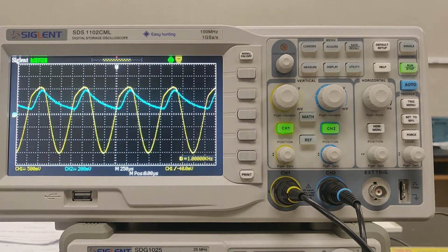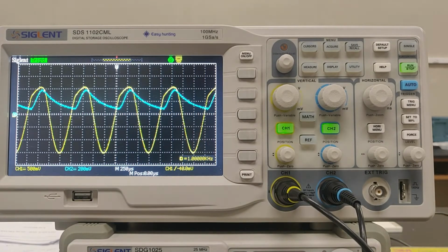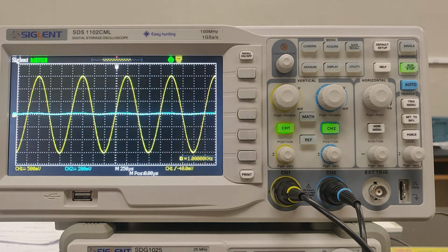So with a larger capacitor, we can see that the discharge is sustained for a longer period of time, such that it can reach the next time the circuit enters the forward bias region. So half of our sine wave starts to look more like a stair step wave or a triangular wave, a sawtooth pattern. Let me now replace the 100 ohm resistor with the 1000 ohm resistor and see how the circuit changes again.